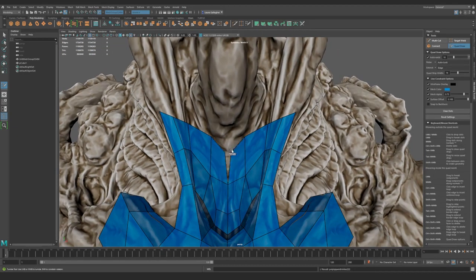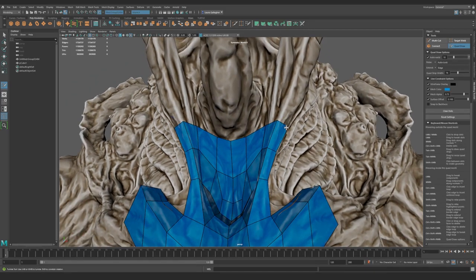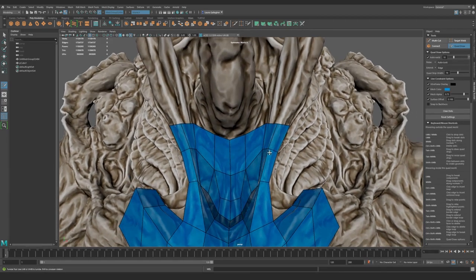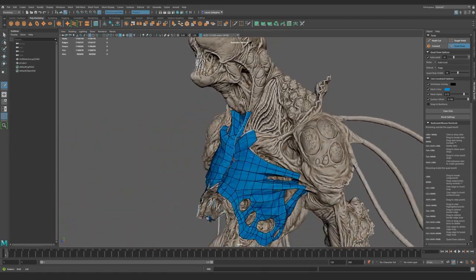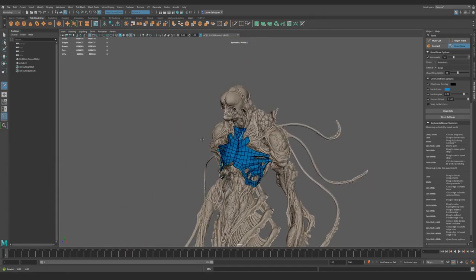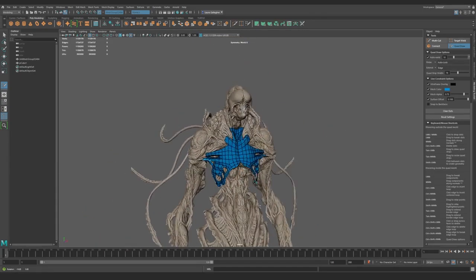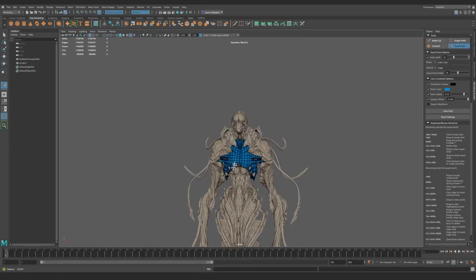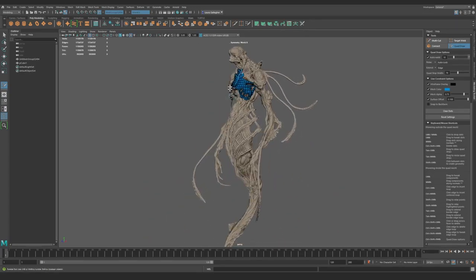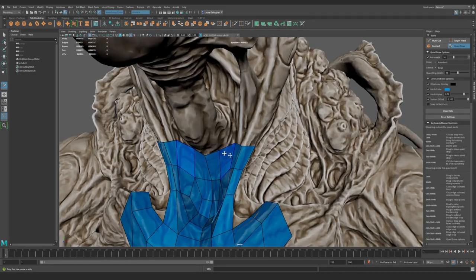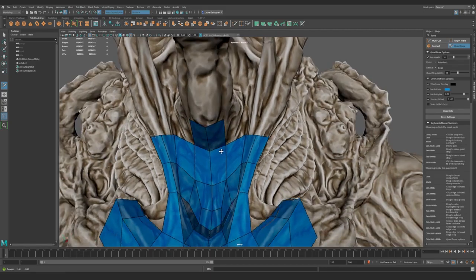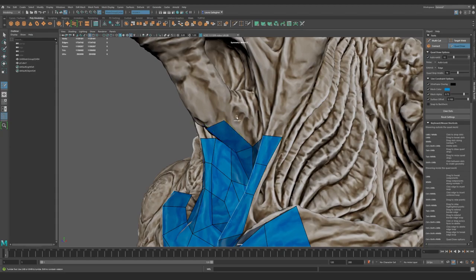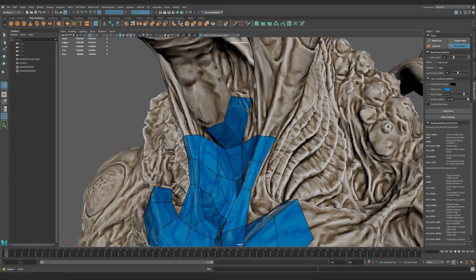Because this is a low res, right? There's certainly a set size to these polygons that we're more or less trying to hit, mentally speaking. And so at some point, with tiny little holes like that over the creature, you're just thinking, is this really worth trying to capture? I would wager that it probably is because this is close to the head of the character. So this is starting to get within the zone where we want our polygons to look smaller and smaller. But let's just continue here with the neck of the creature, and we may come back to that later.